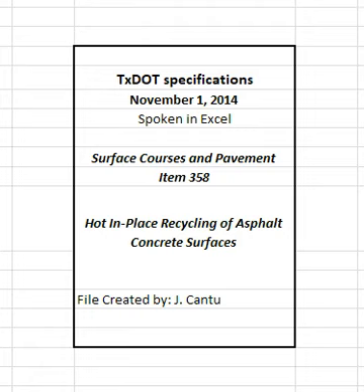3.4 Field Laboratory. Unless otherwise shown on the plans, furnish a mobile testing laboratory meeting the requirements of TEX 237F and a Level 1A certified laboratory technician qualified under the department's approved program. If fresh HMA is added, perform the tests necessary to control plant production.